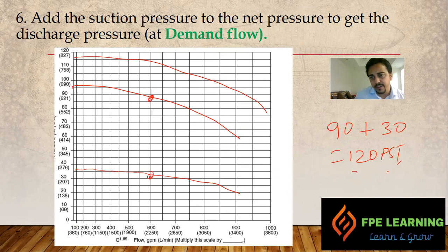This is why I always emphasize to my students and those who come to my facilities for the trainings that whenever you are selecting a pump, give the complete detail to the pump manufacturer and tell them, see, this is an above ground tank and we have this much suction pressure. Based on the height, kindly recommend the best one. While doing that, you will be selecting a highly efficient fire pump. The energy consumption will be lower, because if the pump needs to give less pressure, the energy consumption is also less, right? So we have to keep those in mind based on the factors.